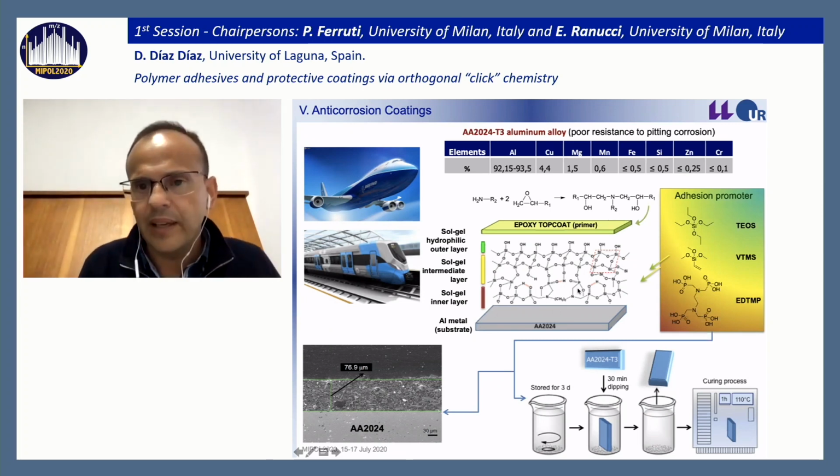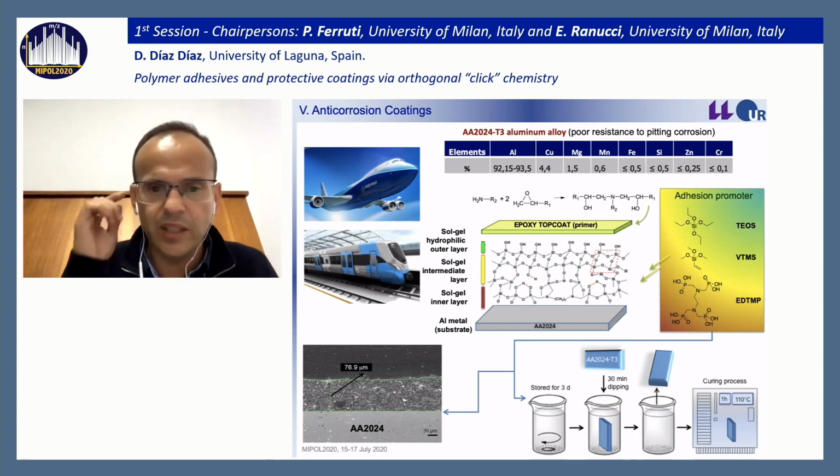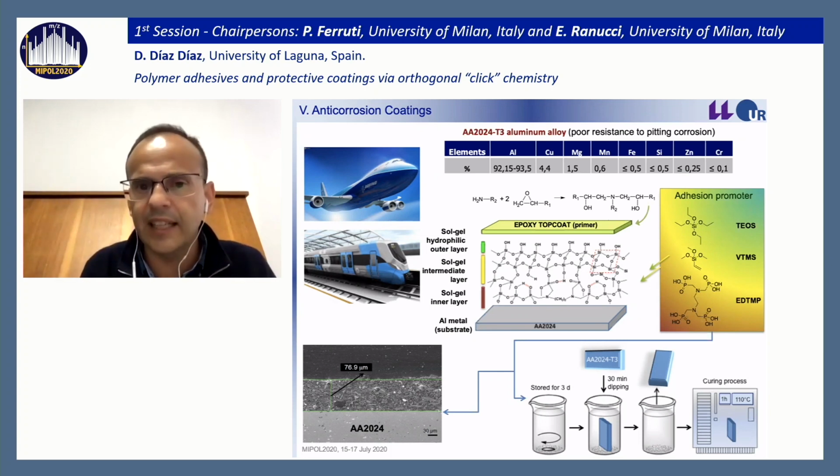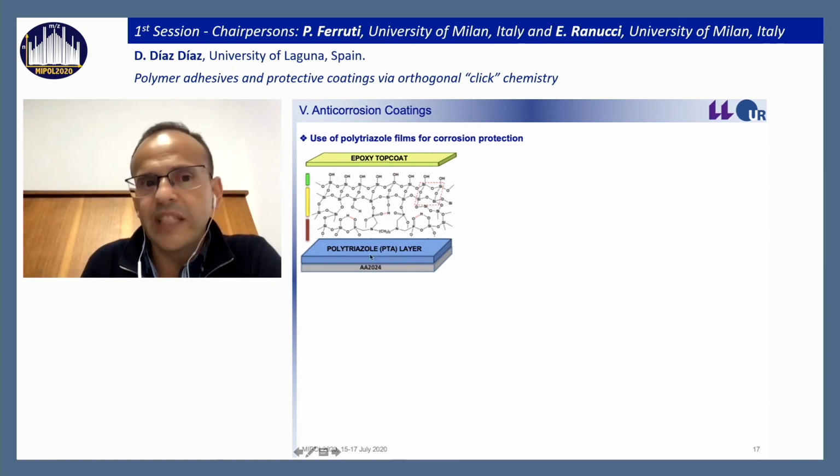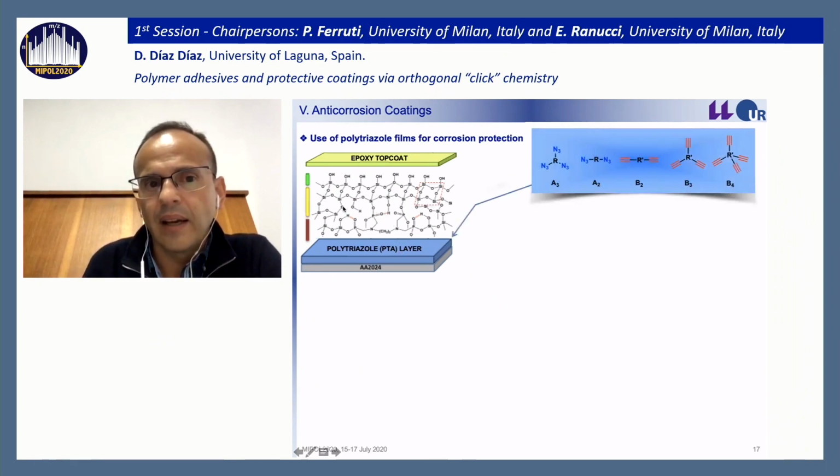What is the problem? Most of this adhesive uses aromatic solvent, and there is a lot of effort trying to get rid of this solvent and trying to find alternatives that can maybe make the connection between these two layers easier or faster or more economic. One of the things we thought is that we can replace, or put directly, a polytriazole layer between the aluminum and the organosealant.